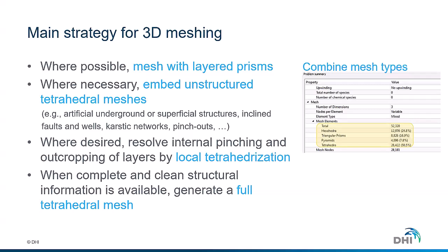If you have more finite elements, there will be more nodes, and for every single node, we have to solve an equation. So you are indirectly increasing the size of the problem and therefore reducing the performance of your simulation.